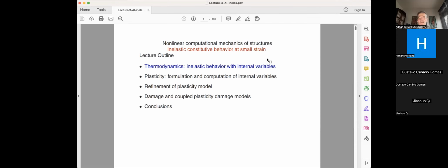That's a generalization of Tresca criteria. And basically, I show you that even though it is a 3D model, it has only one mechanism, which is related to the shear deformation, or which could be very nicely expressed with the deviatory part of the stress. And so you only have this mechanism triggering, so it comes down to really one mechanism.